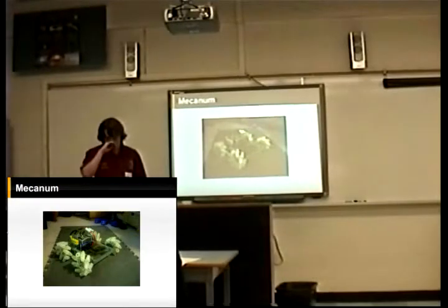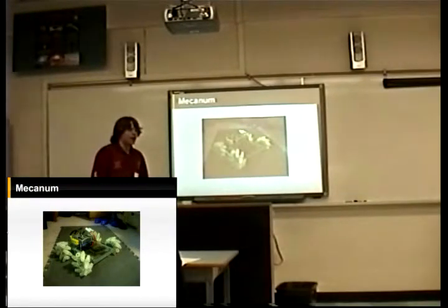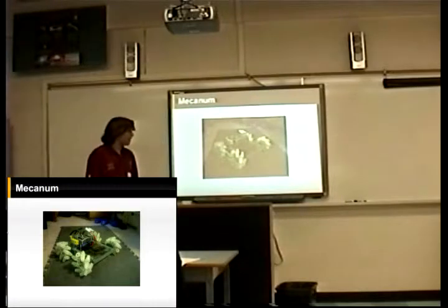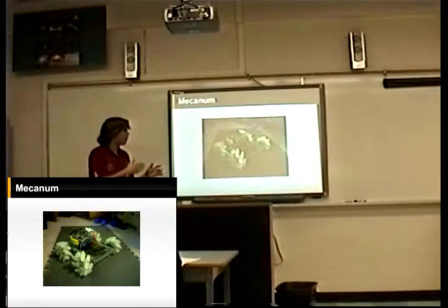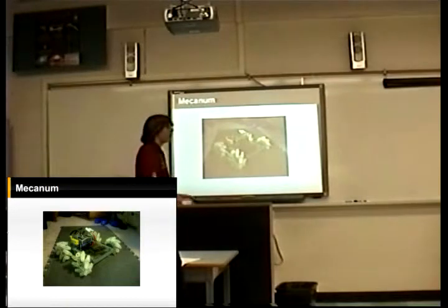Okay. So Mecanum wheels. If you haven't seen a Mecanum wheel before, they are really, really cool. The most prominent team who had them last year was probably Team 188, although a lot of teams use these kinds of wheels. They're kind of like Omni wheels, but the rollers are oriented at 45-degree angles to the ground. So I wish I had a video of how they drive, but basically...